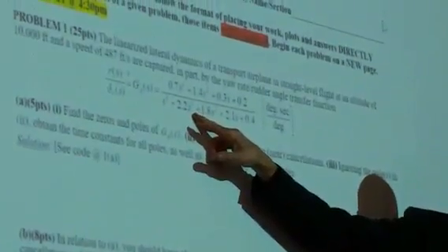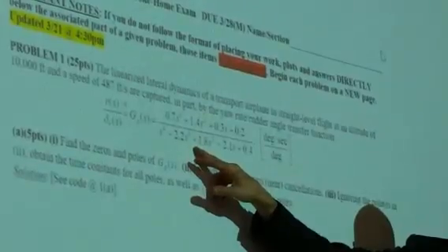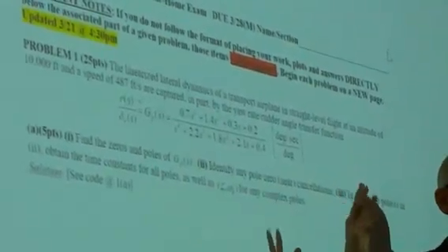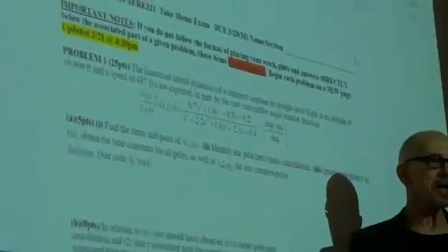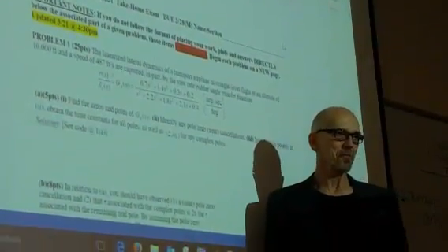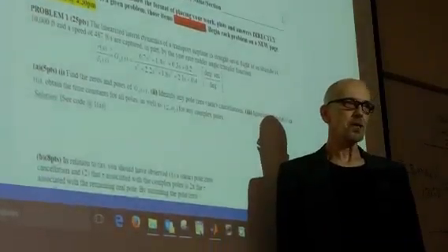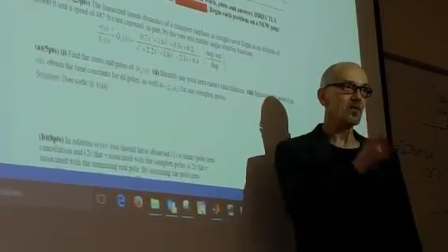This is a fourth order system with three zeros, but when you have a zero canceling a pole, this gets knocked down to second order, this gets to third order. That's it, but be careful because you have to make sure the static gain is still the same. That's the only key.